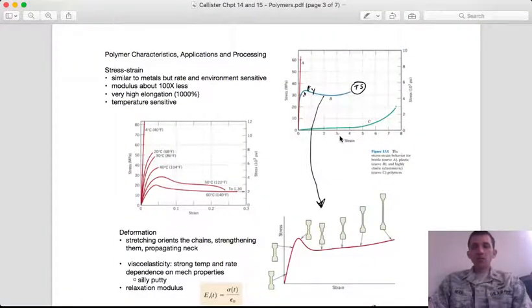Here, we're not looking at 0.0 anything. We're looking at 3, 4. This is times. Remember, strain is a ratio of delta L over L. So to have a strain of 4, right, you are elongating 4 times the length of the original. And so for an elastomer, you can see the modulus is very low, and the elongation is off the charts until fracture. And also see here that the elastomer gets stronger as it approaches fracture for reasons that we'll talk about later.